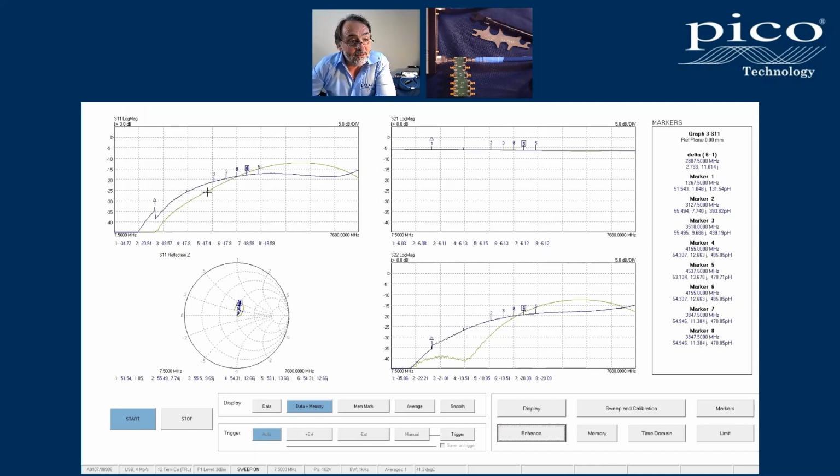So this measurement was made inclusive of the feed lines as mismatch and as loss. I've tried to compensate the loss and the phase delay of the feed lines as best I can, but I haven't compensated the match of the feed lines, and that's why this measurement is not so good. This measurement will be the more reliable measurement of the match of the two matches.